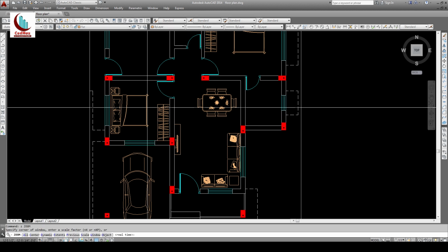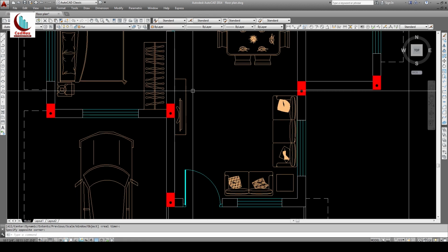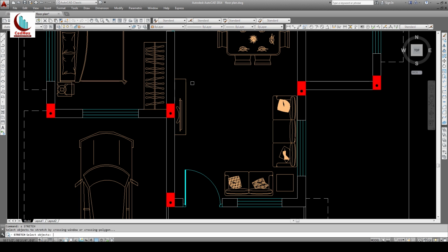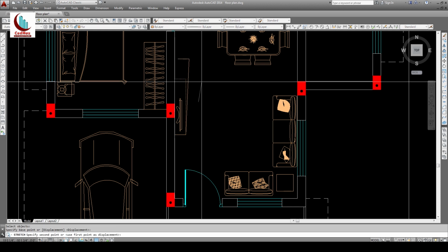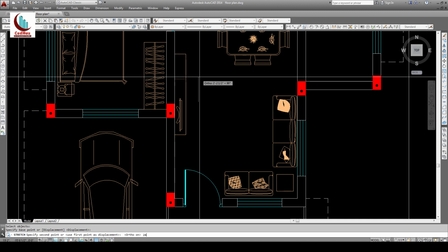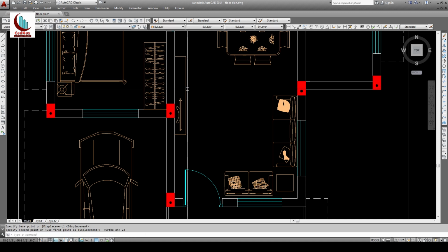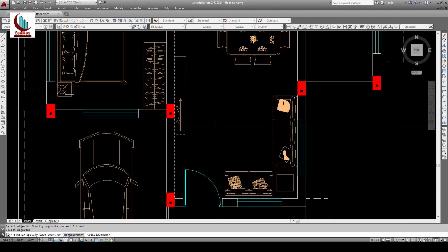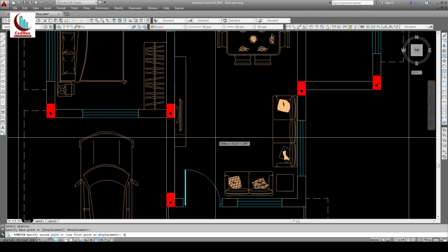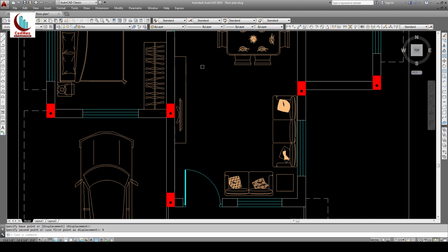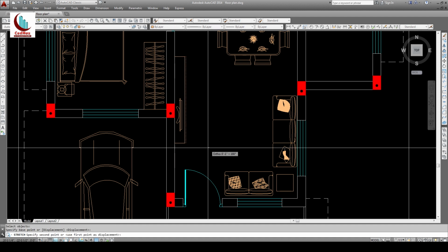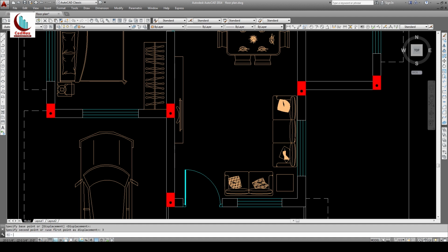In the provided drawing, the TV unit looks a little bigger. You can always stretch it like this. Keep ortho on, say 2 feet. Okay, maybe this one 9 inches, and this one it is slightly narrow like this. Okay, now move the TV slightly this side.